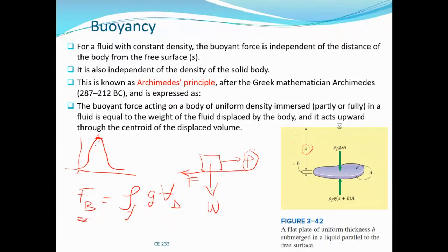So once P is greater than this value of the limiting frictional force, okay, then the block will be in motion, and then the value of the frictional force will begin to reduce because it is in motion. Then you will now have dynamic frictional force. Before, you had static frictional force, and this is the maximum value of the static or the limiting frictional force.